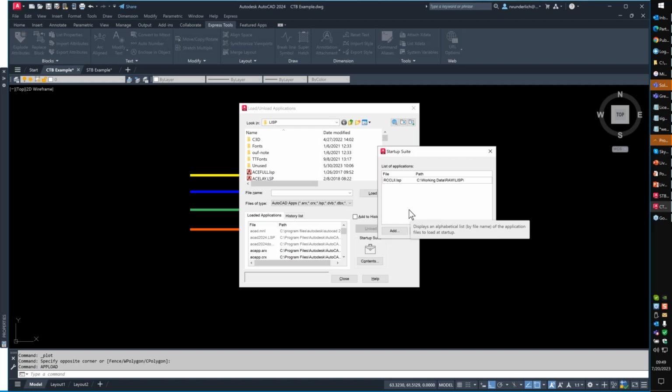I recently had a drawing where all the walls would turn the color of the current layer. As for the way to stop that behavior, Mark, it depends on whether you're in basic AutoCAD or AutoCAD Architecture, because you may have a style override or something else that's causing that. We can figure that one out, but that's more of a technical issue specifically with that drawing. We'd have to dig into it and find out.